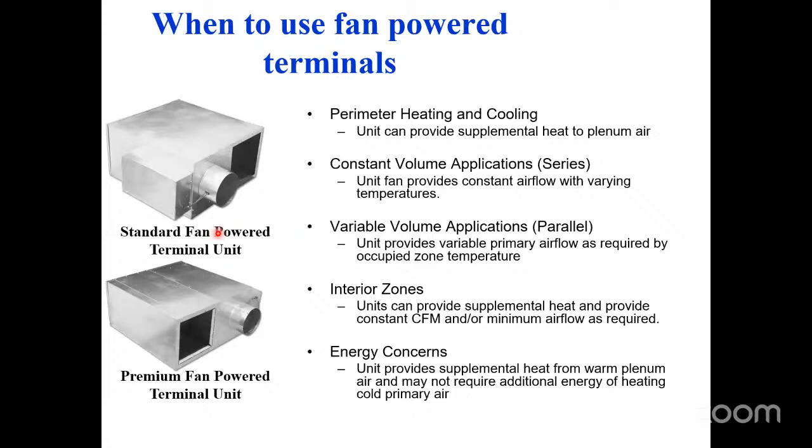There are two types of fan power boxes that we utilize. There is a series fan powered and there is a parallel fan powered box. Series fan powered provides the same CFM out to diffusers at all points in time. Parallel, the amount of airflow will change, and you'll see why in a second.